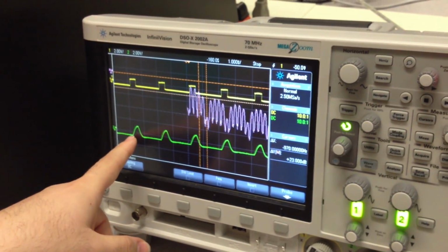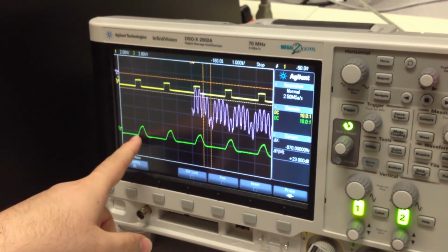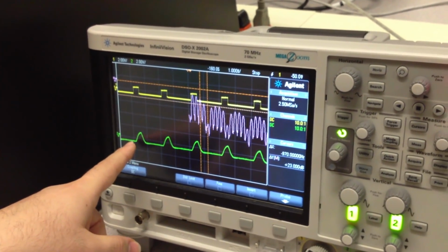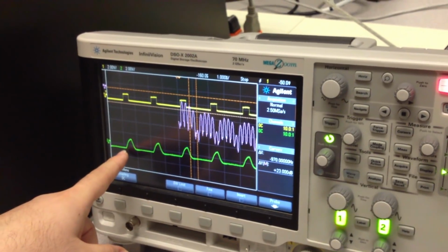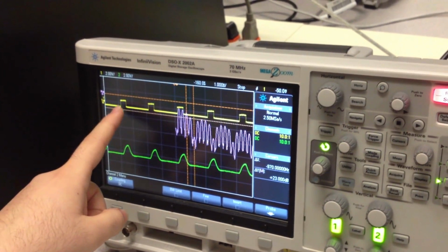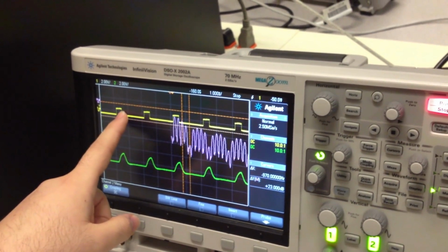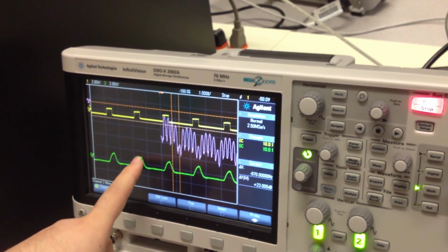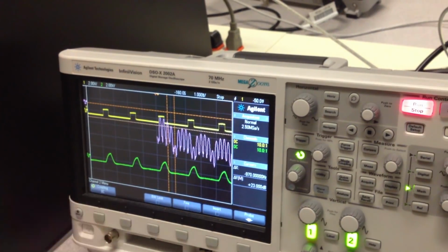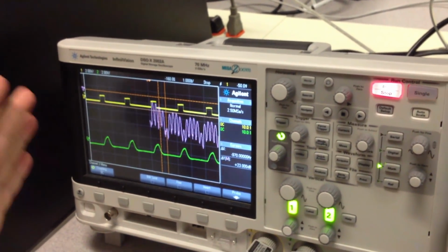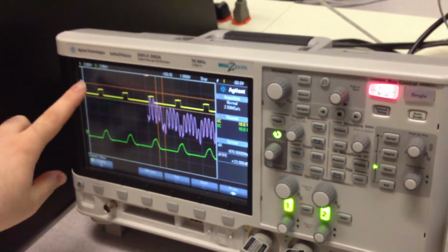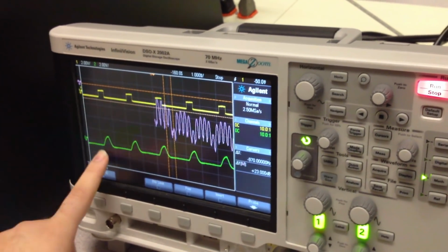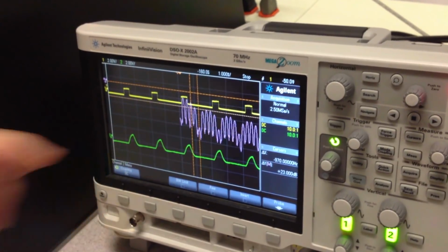If you look carefully, there are no sharp edges. When you apply low pass filtering to a signal, the high frequency components are omitted, set to 0. So the sharp edges, which represent the high frequency components, are gone. It is smooth like that. There are no high frequency components. Okay, so that's the time domain. We input the square wave signal with duty cycle 20%, and we got this signal.